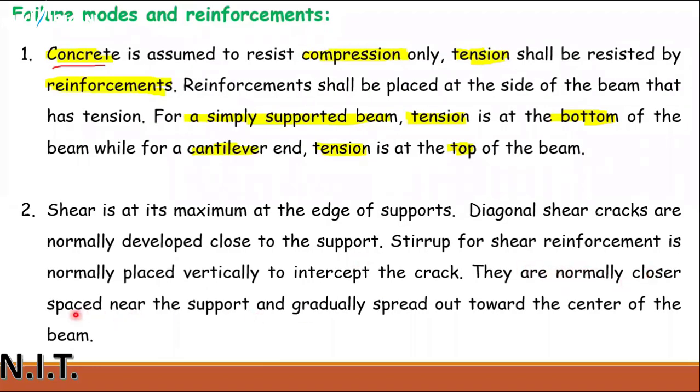These stirrups are normally closely spaced near the support and gradually spread out toward the center of the beam.